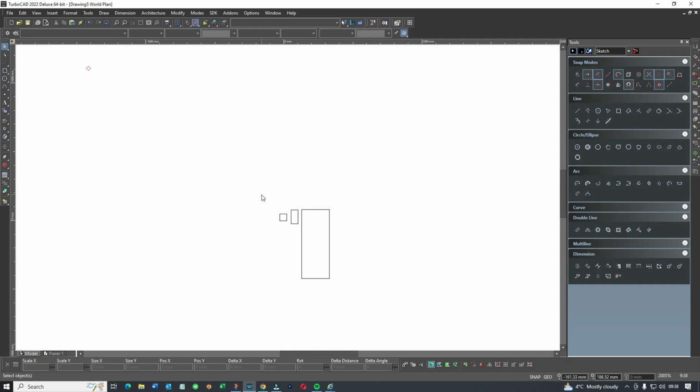So you say, well, 1 inch means 100 inches, or 1 millimeter means 1000, and that's how you introduce a scale. So you can put a city plan on an A3 because it's scaled. 1 inch or 1 centimeter or 1 millimeter will mean 1000, and you have to write the scale at the bottom.